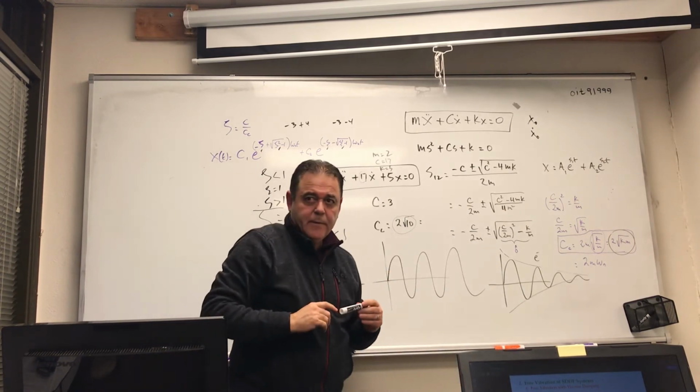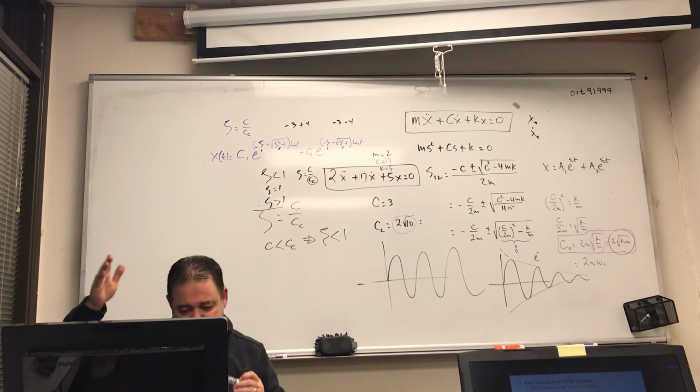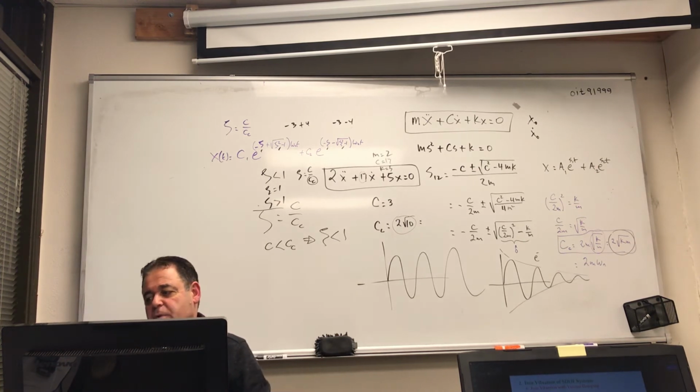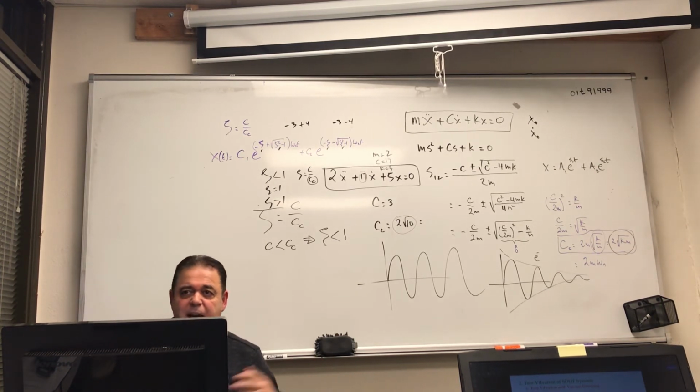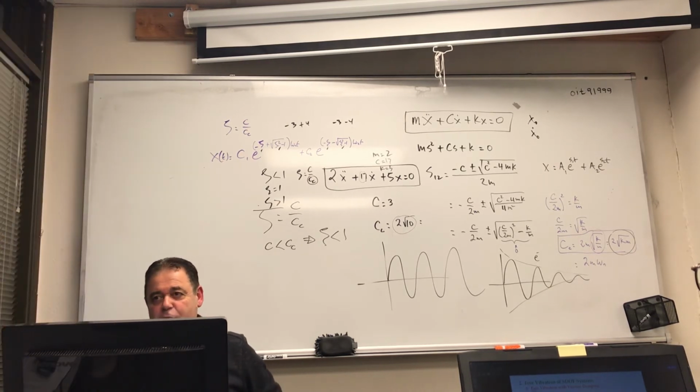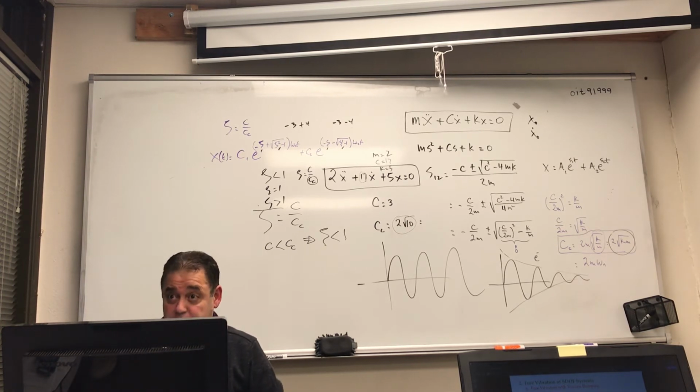Could you compare it to the rebound of a shock absorber? Exactly. When you get a cannon or something like that, you don't want that thing to go back and forth. You want it to be critically damped, or maybe slightly overdamped, if any, just to make sure that you don't get any residual vibration.